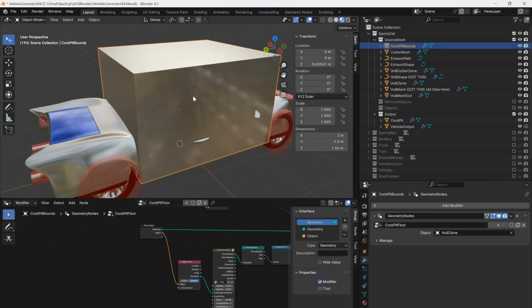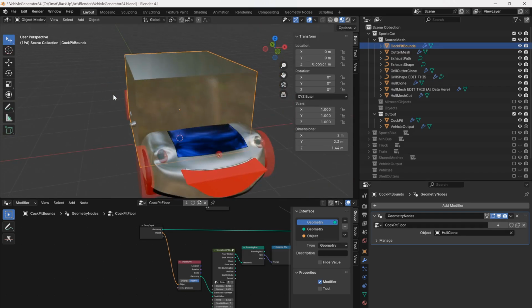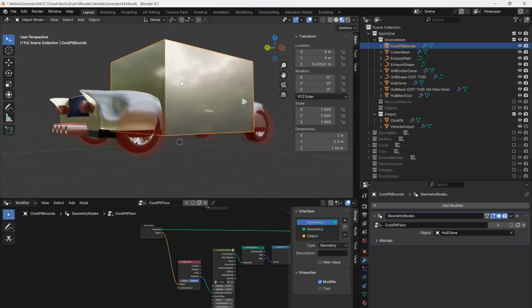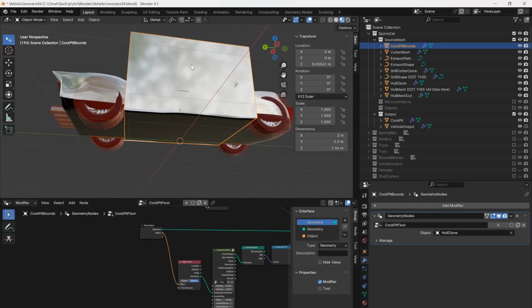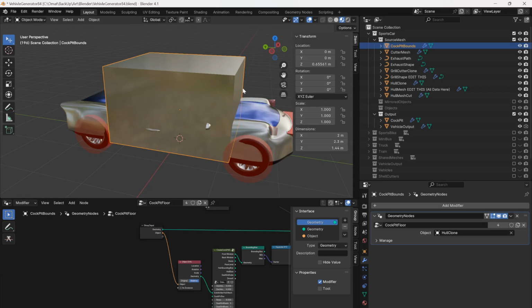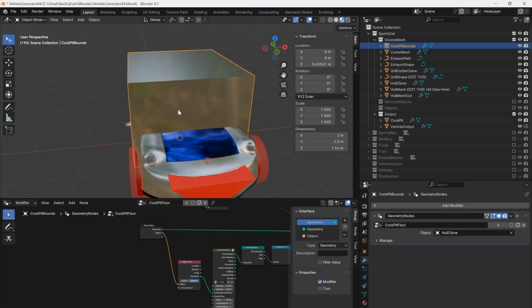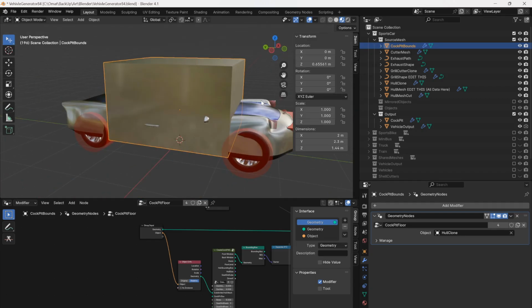which is the cockpit box, which is just a box that I can draw to define where I want to see, because I really don't need stuff in front of this or behind this for the cockpit, and it will make a boolean operation, so it will enclose and make it like a watertight sealed cockpit with another boolean operation.